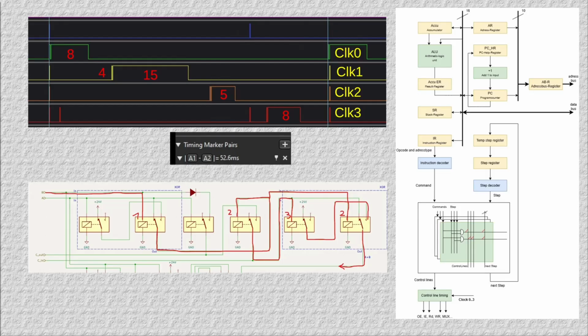And the reason, I'm not 100% sure, but I think that is the reason. The reason is the result register here and the arithmetic logic unit here where the adder is located. And the interesting thing now is that if we start with a new cycle, if we start to add information coming from the data bus to the accumulator, this is done in the ALU.